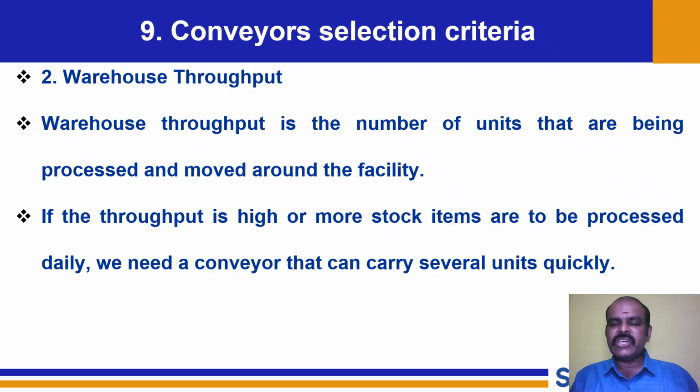Why this is very essential is that conveyor systems are not suitable for perpendicular joints. This has to be thoroughly understood. A conveyor system can be used even for an angular case. Even we can go ahead with some sort of semi-rotation, that is semicircle based, or some arc based transportation is possible. But at any point of time, a plain conveyor can never handle perpendicular movement. But still it can be made. We need to have a different type of pushing based conveyor, but that is not advisable for a fragile product. So we should understand the movement, or the direction of the transport or traverse.